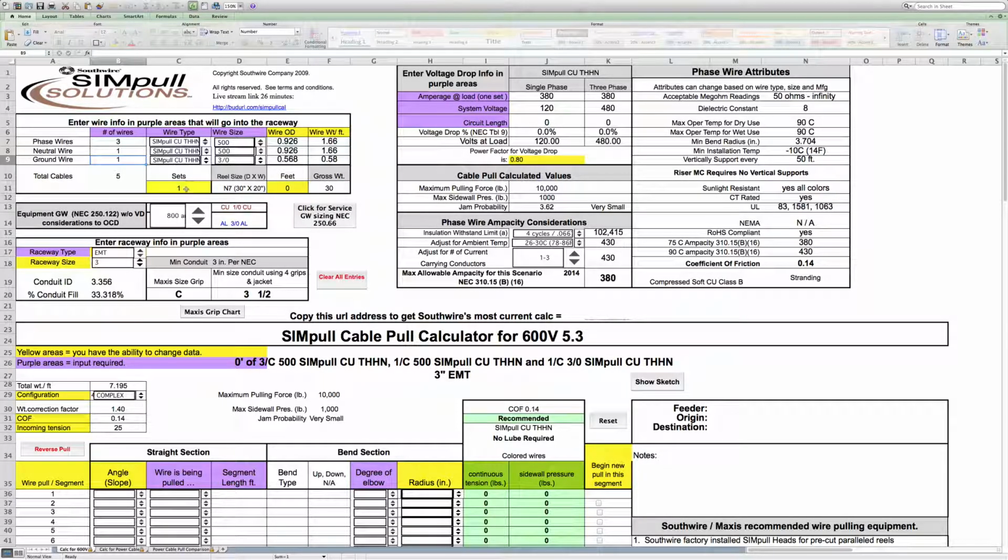All right, if I want to know what size reel all this wire will go on, this information is for that purpose. Say I want to use a 320-foot reel with all those wires on there. That's going to give me a reel size of 40 inches by 27 inches, gross weight of 2375. That would be for one set of all those 5 wires.